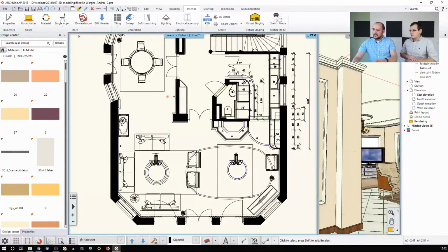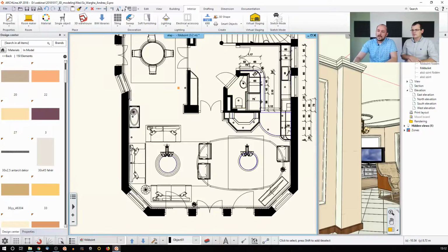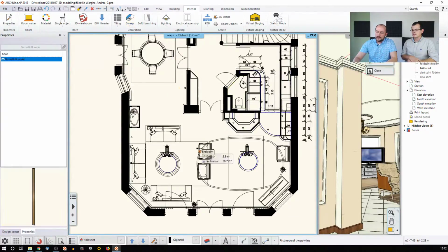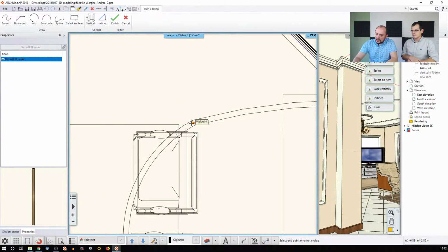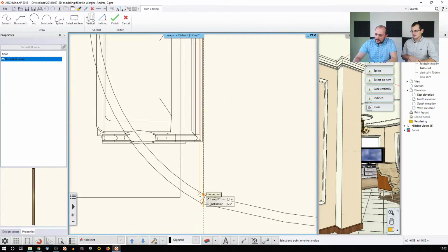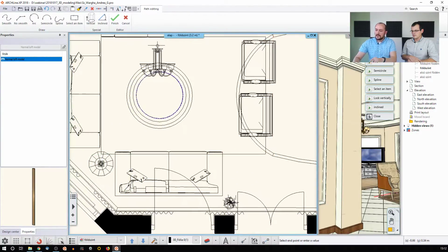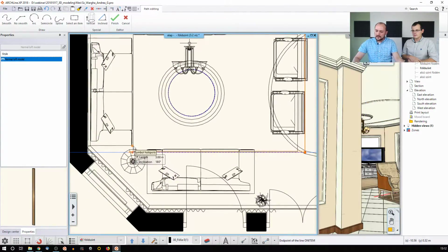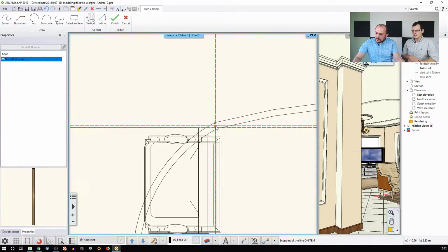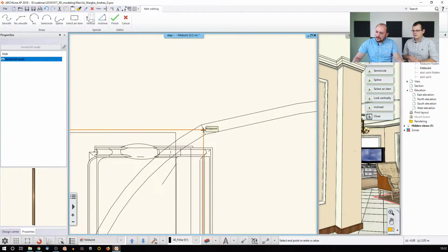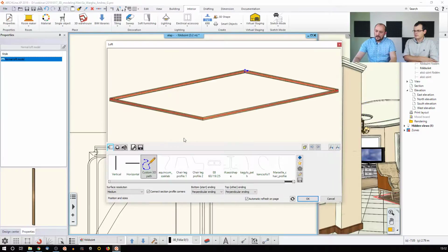So let's just go back and design it. I'm again using the sweep tool, and let's create something rectangular. I will start from the same points, this here and this here. I would like to align it together with the other one, like here. I'm just referencing the original point so I can create a closed loop. And when I hit enter, I get this.